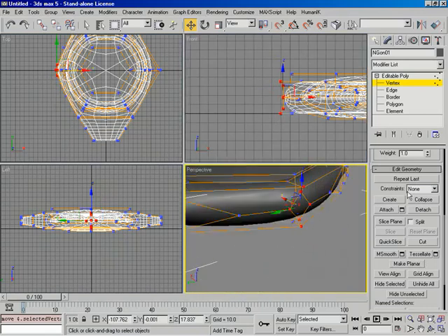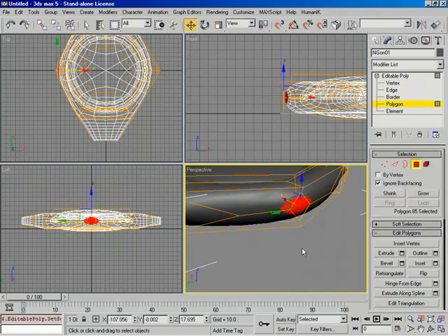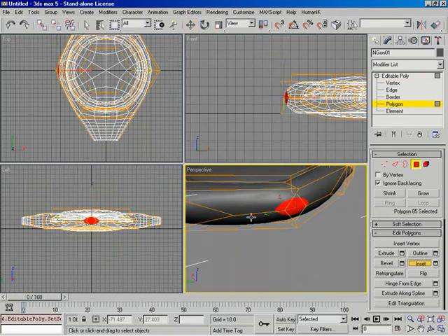Then we can simply come on up here and switch over into polygon mode and grab that polygon right there. With this, we'll start out with a simple inset. I'll do it interactively, just pull it in just a little bit. So right about up, close. The computer's giving me a little bit of slow reaction right here because of all the recording that's going on. So that's pretty good. Now let's do an extrusion. I'll click and I'll extrude this negatively. We'll just go back just a little ways to right about there.